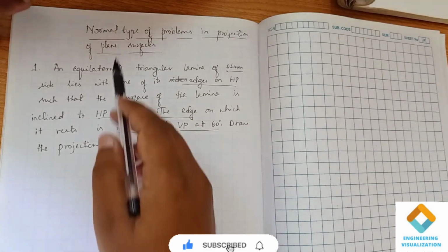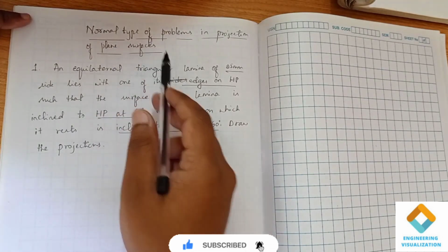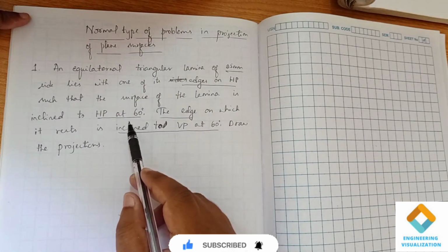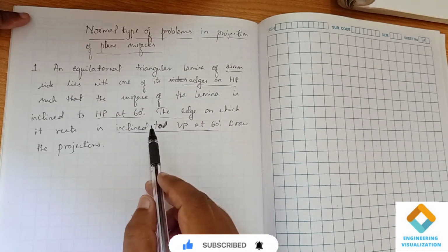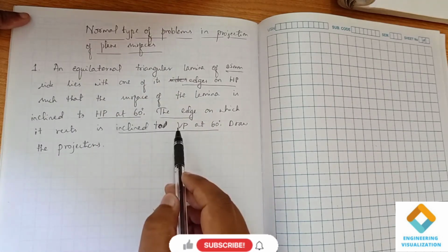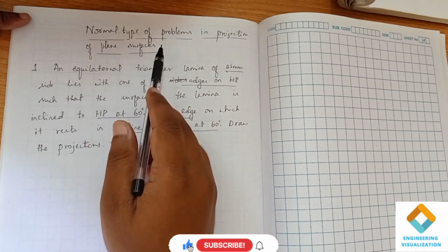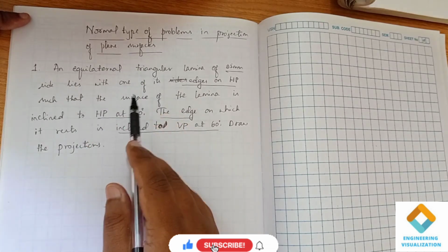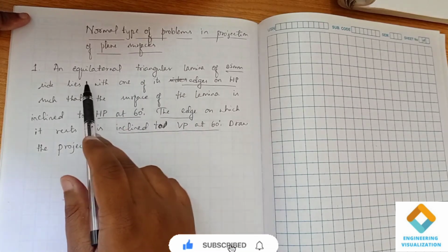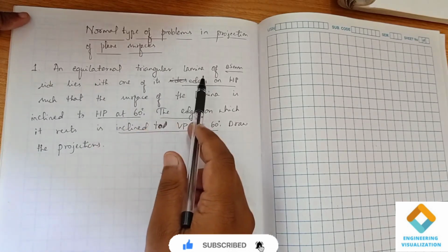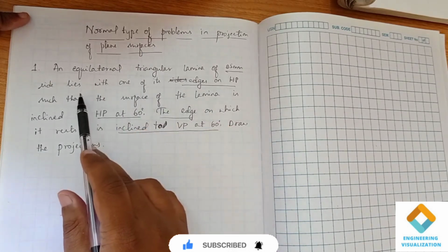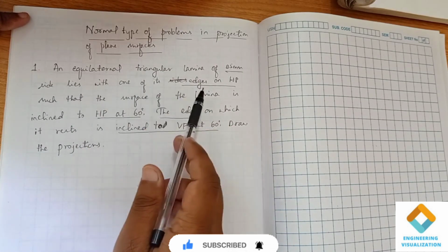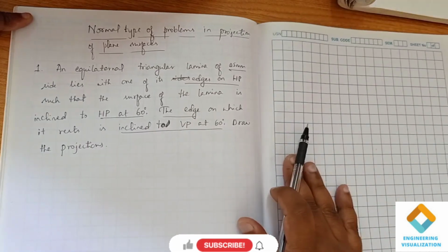So that's the condition for a normal type of problem, right? If the angle of inclination is there with the edge and the same edge has been inclined with respect to both HP and VP, we call that a normal type of problem. Okay, so now we will proceed with the first position. We need to construct an equilateral triangle of side 25 with one of its edges on HP. Okay, so I'm going to proceed with the solution.